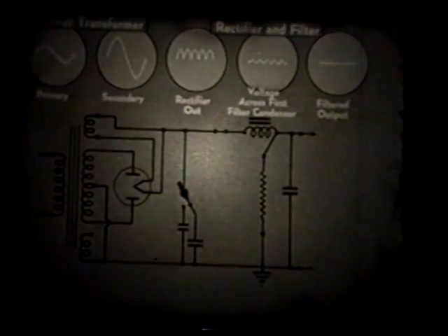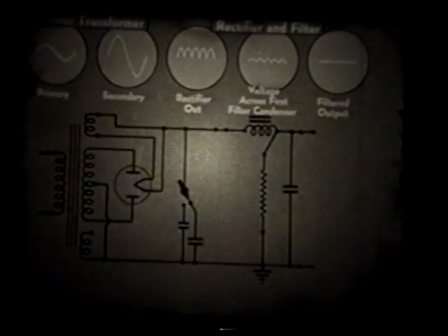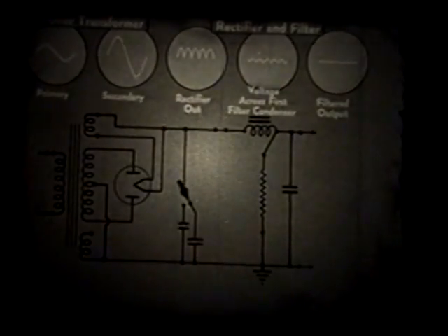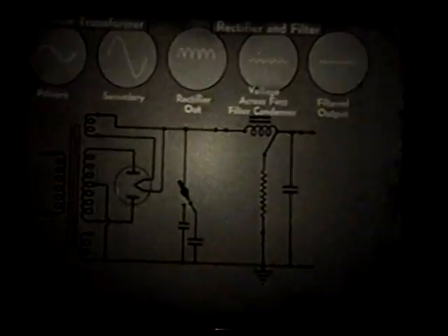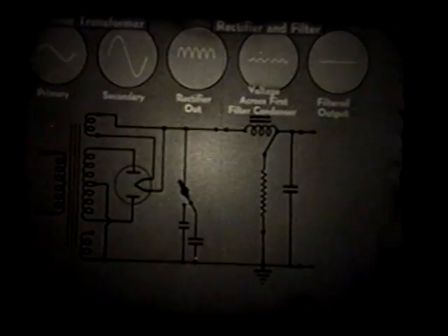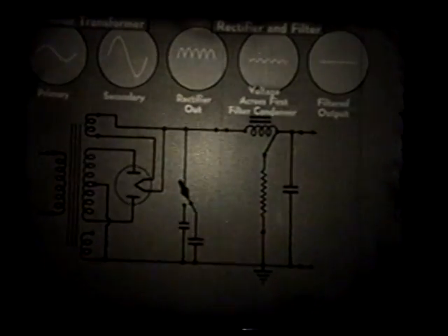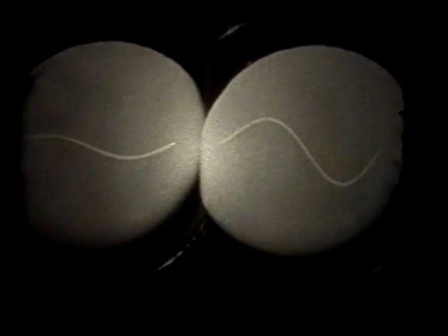By knowing what waveforms to expect in various circuits, the skilled oscilloscope operator is able to check through and locate faulty sections of power supplies, audio, radio, and intermediate amplifiers, and other more complex circuits. Let's apply this idea to checking an audio frequency amplifier for distortion. Here is the waveform of the original audio signal. Compare it with the waveform taken off the first stage. In spite of the increase in amplitude, there's little distortion at this point.